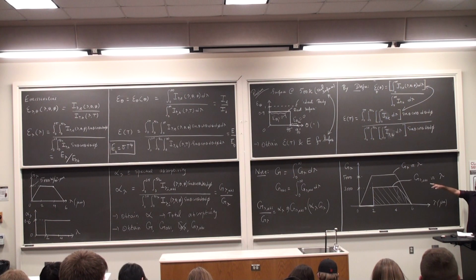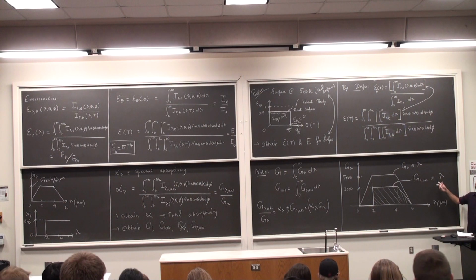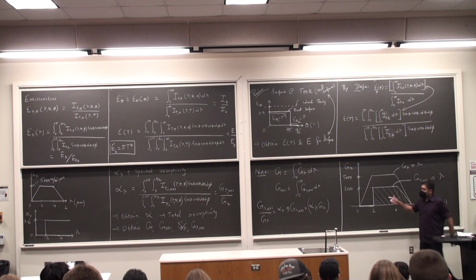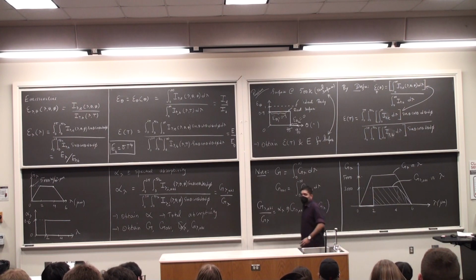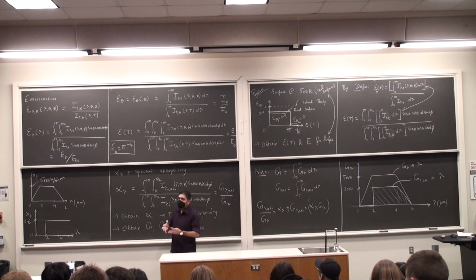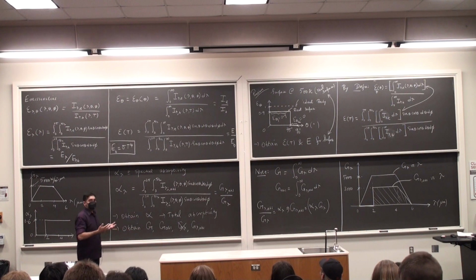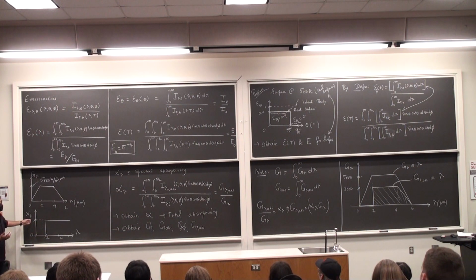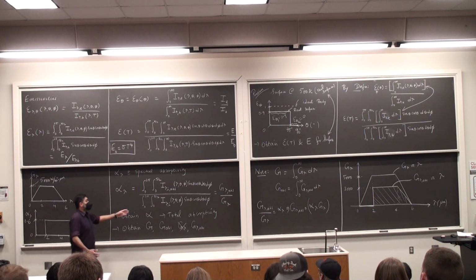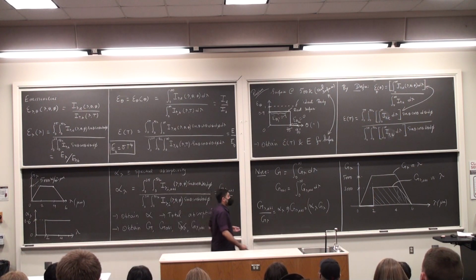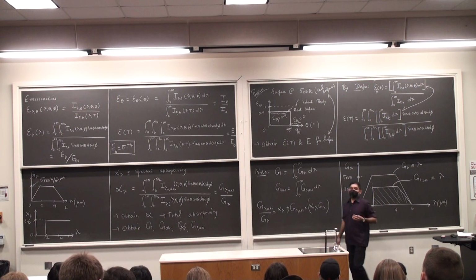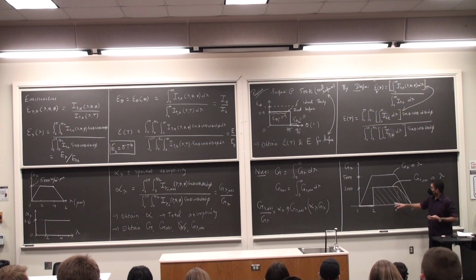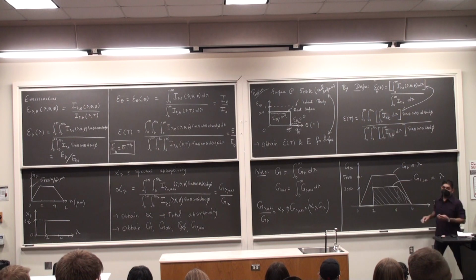I have those two plots. The first plot is G lambda versus lambda. I need to find G lambda comma absorbed. By the definition, this is just alpha times G over that particular wavelength range. From 0 to 2, alpha lambda is 0. From 2 to infinity, it is 0.6. But I don't need to go to infinity because after 6 micrometers, my spectral irradiation drops off to 0. So from 2 to 4, it's going to be 0.6 times 5,000.